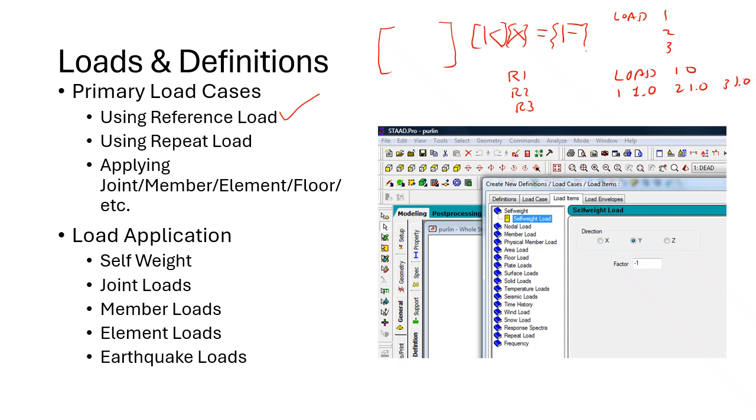It means the load combination 10, load 1 is 1 time. This is the load factor. So first is the load ID, 1 is a load ID, and then the factor, by how much it has to be multiplied. Like in the American standard, we have 1.2 dead load plus 1.6 live load, or in European 1.35 dead load plus 1.5 live load. So these are the load factors.